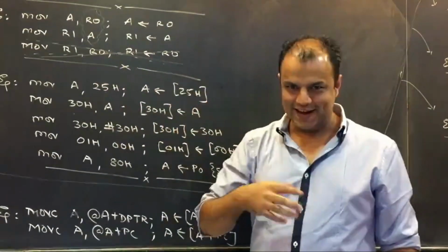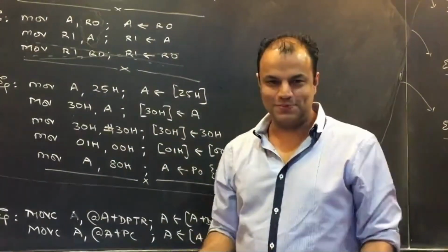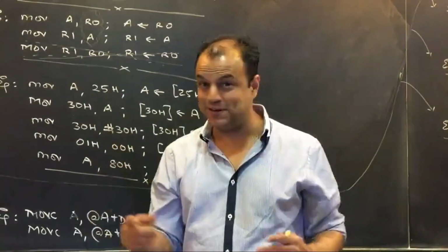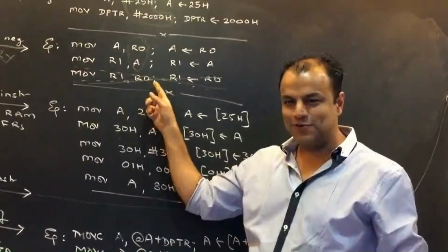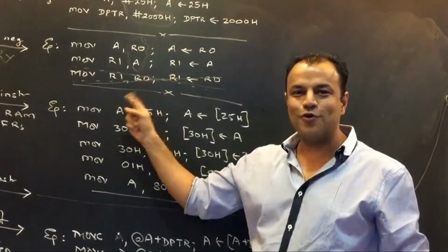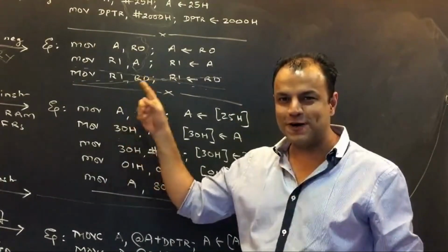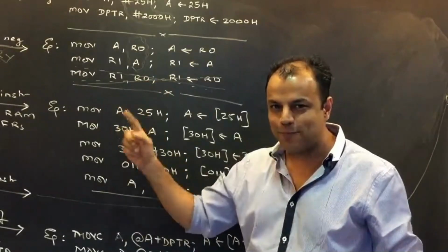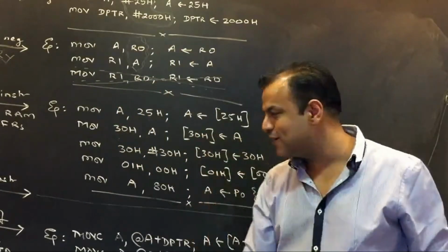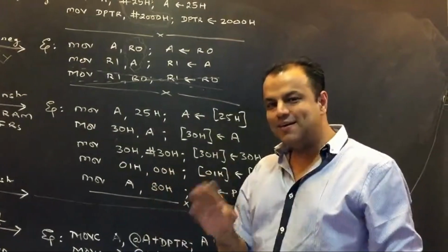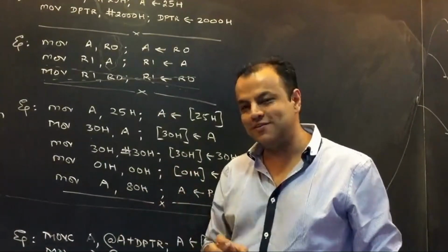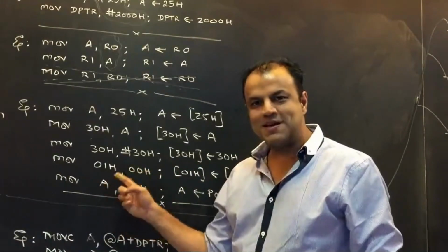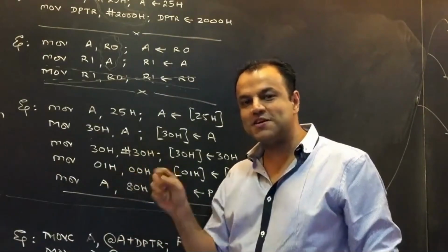It does the same thing, but this is allowed, this is not allowed. And I gave you the reason. I never say anything without a reason, because I'm supposed to teach you. I'm not supposed to just tell you. There's a big difference. If you write MOV R1, R0, this creates 64 opcodes, because for every register, there is a different opcode. Registers are part of an opcode, but these are numbers. Numbers are never a part of an opcode. They are written separately as operands. So because these are numbers, writing these two numbers in one instruction is allowed.